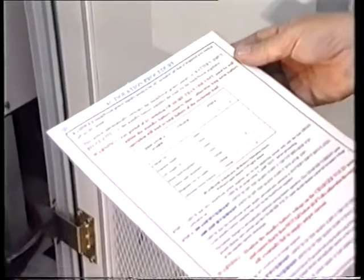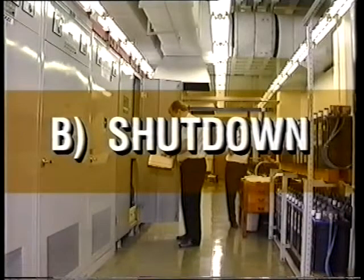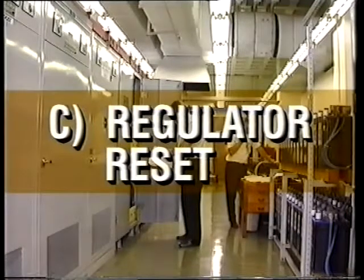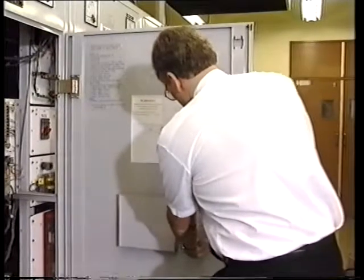There are 4 main operational procedures associated with a buck-boost power supply. A. Startup. B. Shutdown. C. Regulator reset. And D. AC isolation. To assist the operator, these 4 procedures are detailed on a set of cards located inside the door of each